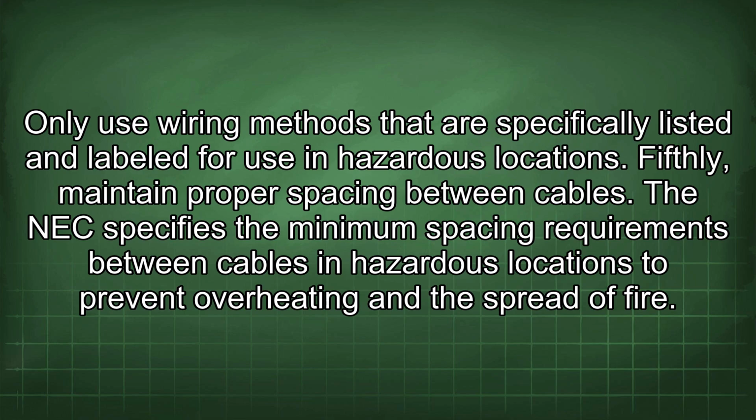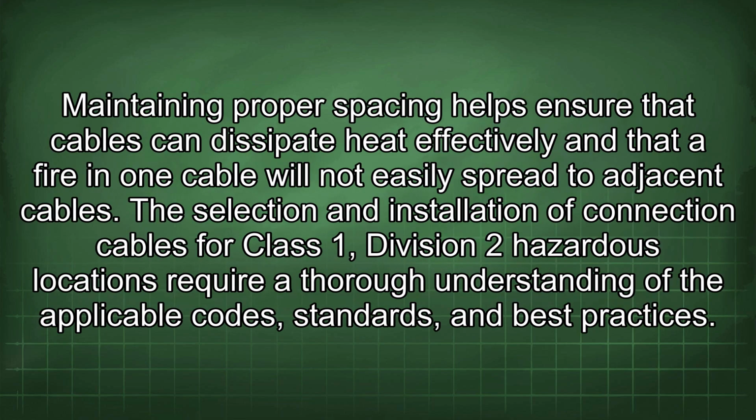Fifthly, maintain proper spacing between cables. The NEC specifies the minimum spacing requirements between cables in hazardous locations to prevent overheating and the spread of fire. Maintaining proper spacing helps ensure that cables can dissipate heat effectively and that a fire in one cable will not easily spread to adjacent cables.